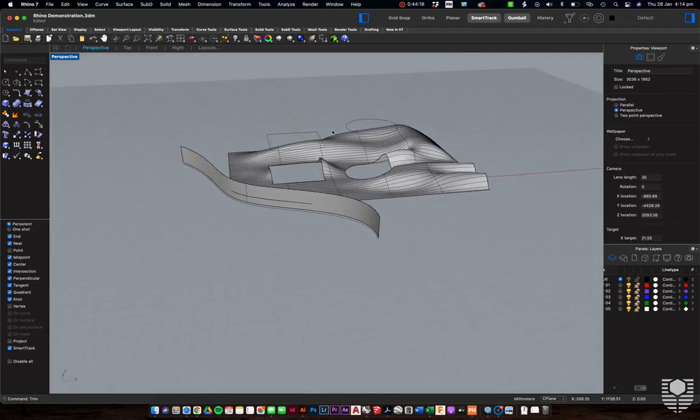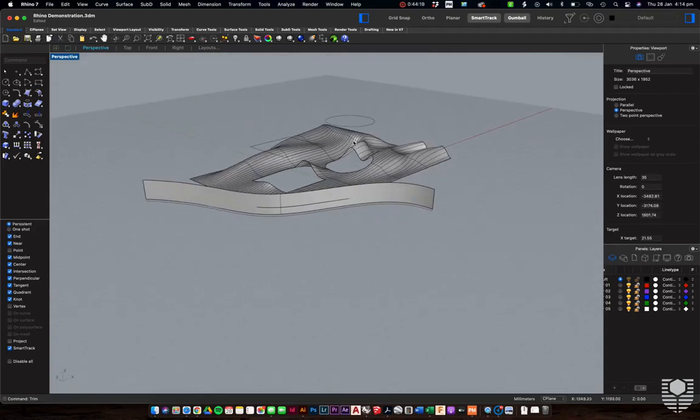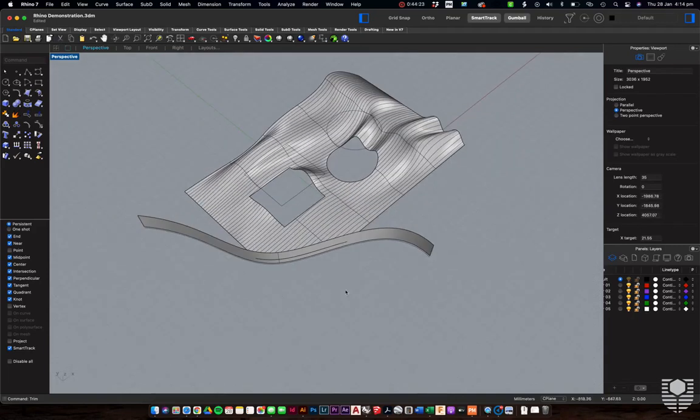So I've now used that circle to trim exactly down inside my surface here. That square is doing the same, and this ribbon has trimmed off that edge piece as well. So it's the same as your split command, but it deletes the objects.